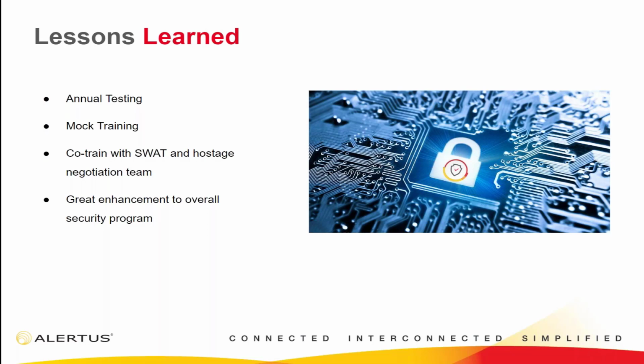Line level audio input is enough for our text-to-speech component to verbally express that emergency alert over the speakers. But from the triggering standpoint, utilizing the fire panel to trigger the Alert Asst server to distribute the message, we are using an RS-232 feed to be able to pull that data and then distribute the appropriate message accordingly from there.